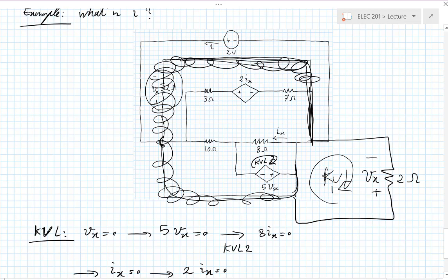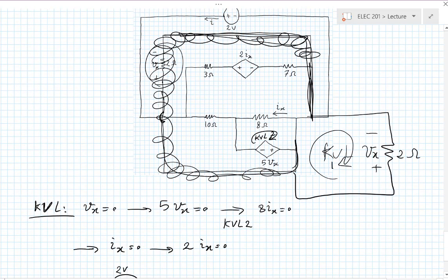I did something very, very rigorous. I did redraw the circuit, if you want, in a way that made it easier on me. And I started applying KVLs and KCLs. It just so happens that one of the KVL equations just had one unknown in it. So I didn't need the other KVL equations before I could solve this one.